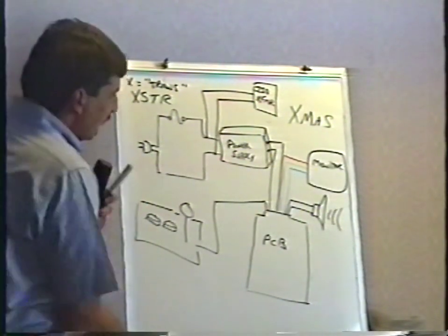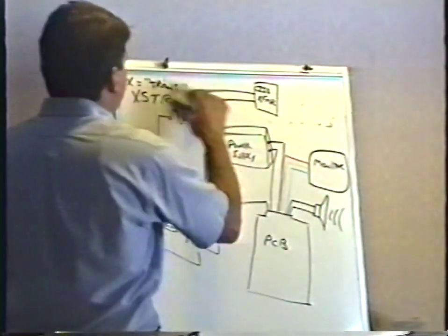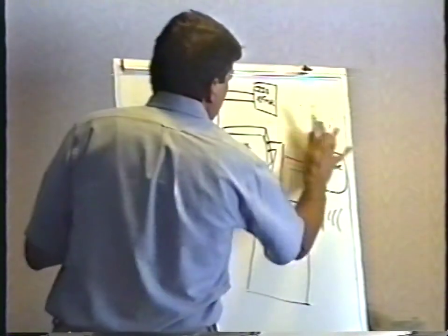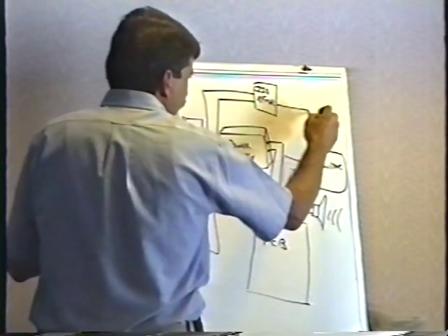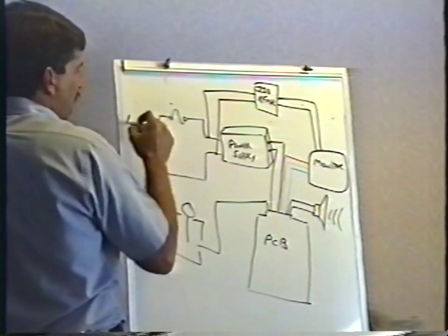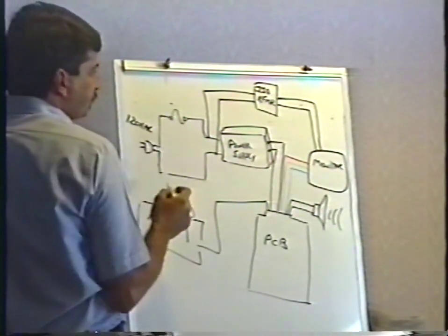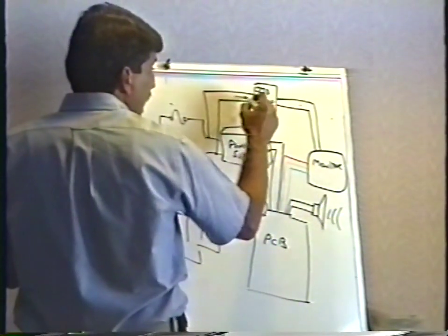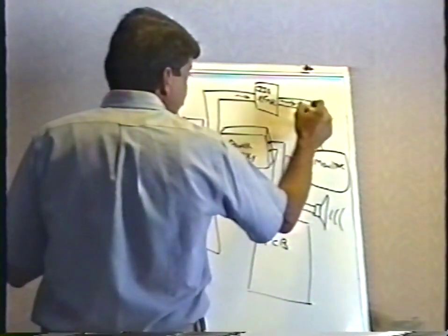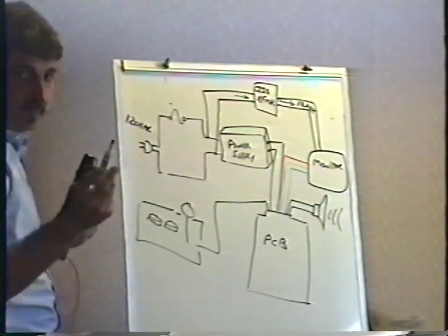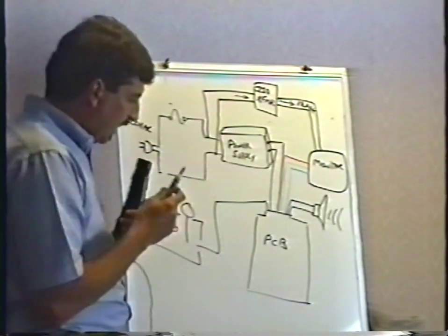So anyway, the isolation transformer, not something that never ever fails, really. The isolation transformer is then used to power the monitor. And of course, this is the 120 volts AC. The isolation transformer takes 120 volts AC in and gives you the exact same thing out, but it is isolated. It's a safety transformer. I mentioned it to you before. I'll cover it again in just a little bit.